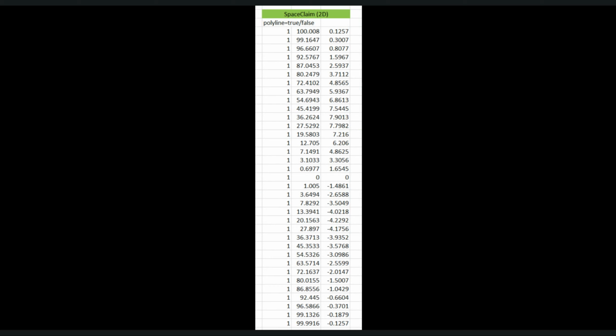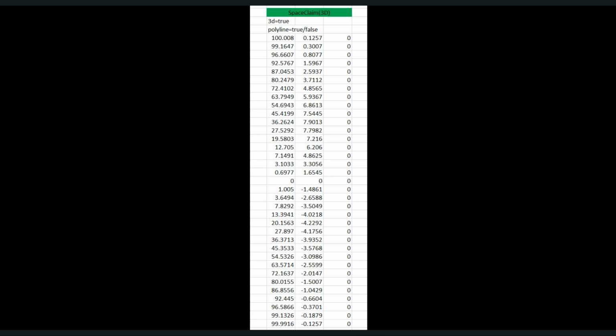Since this is a 2D format, no Z coordinate is required. All points with the same group number belong to the same curve, while a different group number starts a new curve. The 3D format is even simpler than the 2D format.